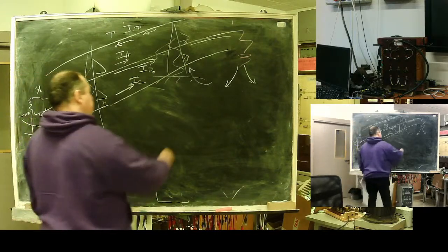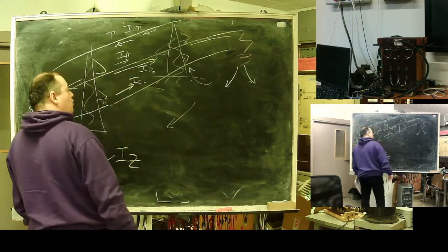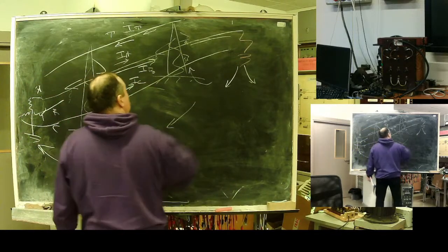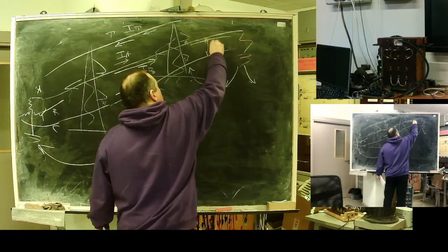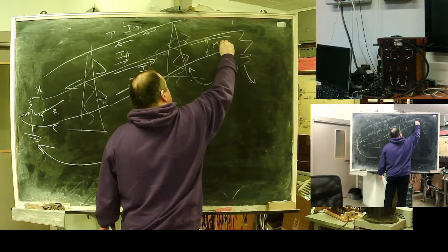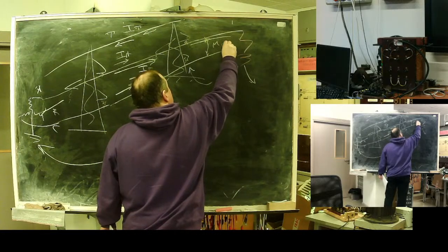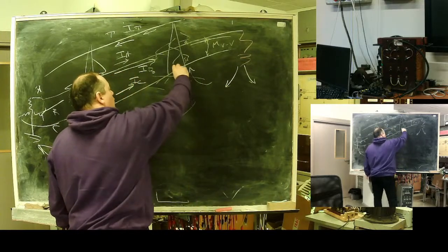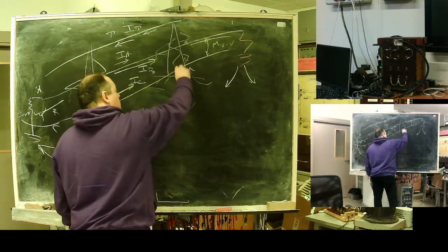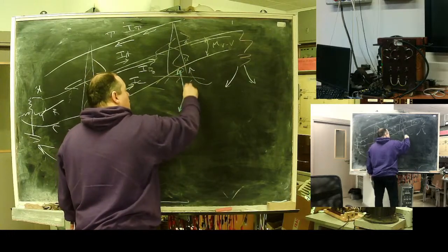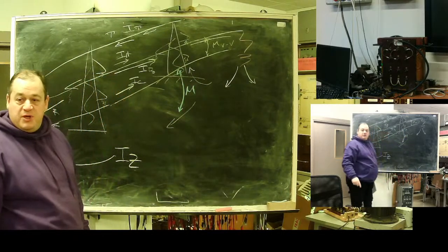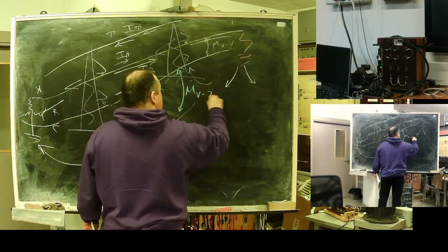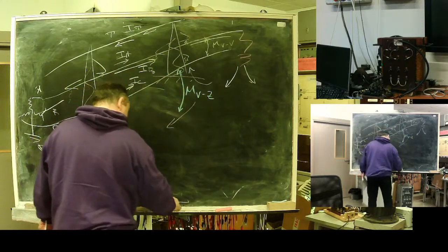The problem is complex because first you need to account for wire to wire inductance, but that's not all. You need to account for mutual coupling between wire and the ground current, and that's not all.